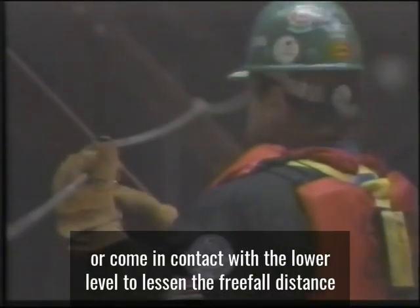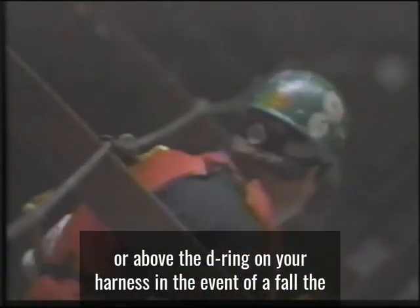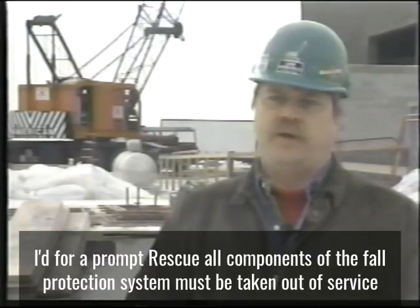To lessen the free fall distance and ensure that the lanyard won't interfere with your movement, the tie-off point should be at or above the D-ring on your harness. In the event of a fall, the standard requires the employer to provide for a prompt rescue.